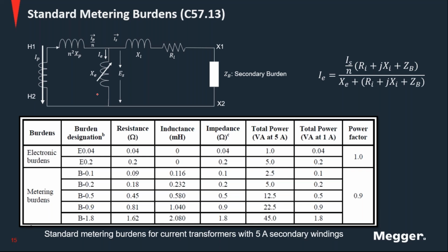Other things have been mentioned here. For example, you do a winding resistance test on the CT and you don't perform a proper demagnetization, or sometimes you do perform the demagnetization, but some CTs have too much core, and then the demagnetization doesn't work as intended, and you will have problems with the increase in the excitation current. So there are many different factors that can increase the excitation current. I just mentioned a few of them.